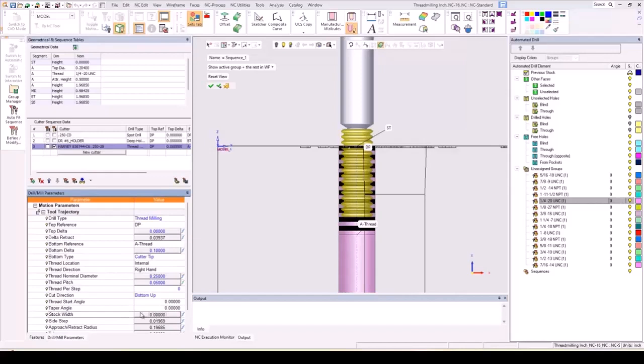Now, stock width, this is going to be based on how you drill in your final. So in this case, we have a 250 hole. We have a 204 drill. So the remainder, the difference of that divided by 2, would be what we put in here if we were trying to be exact. In this case, I'm going to use 20 thou. I'm going to use a side step of 5 thousandths.